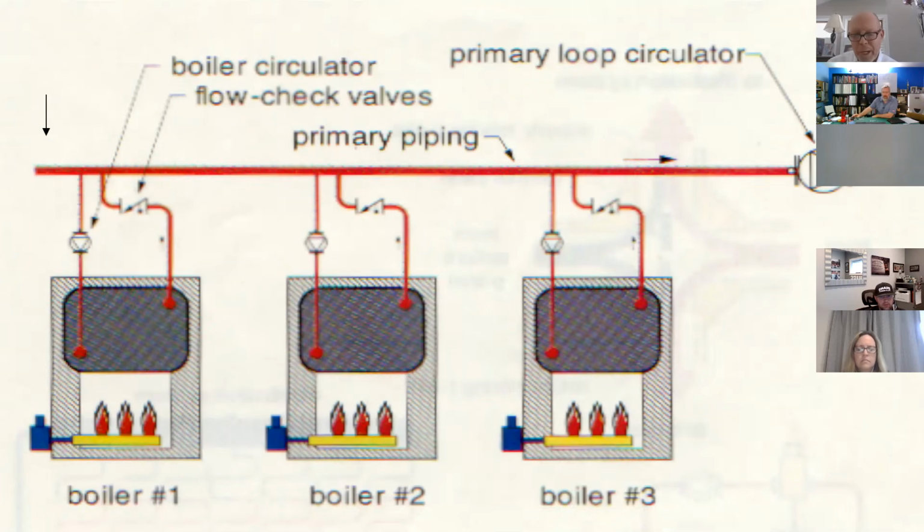Another quick example I'm just going to fly through is a 1-pipe primary, secondary, but it's really not recommended. You'll see it out in the field, but it has some built-in potential difficulties. So let me run through a quick example. I have a 300,000 BTU boiler that's getting replaced with 3 smaller 100,000 BTU boilers. My primary distribution pump is pumping 30 gallons a minute, designed at 190 degrees supply on a design day with a return temperature of 170.